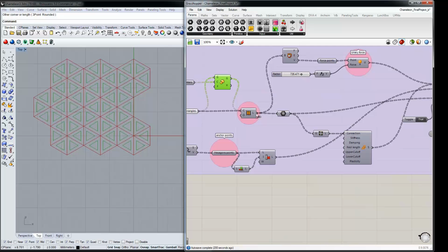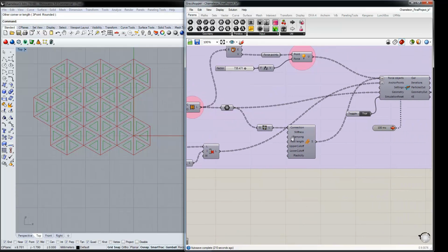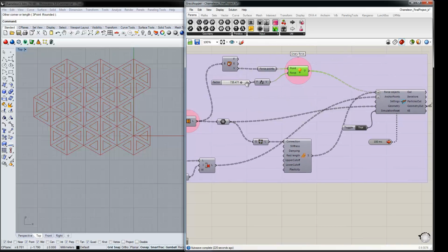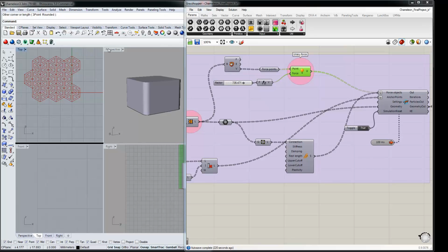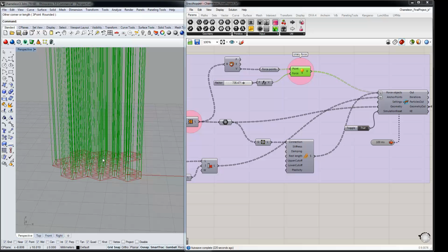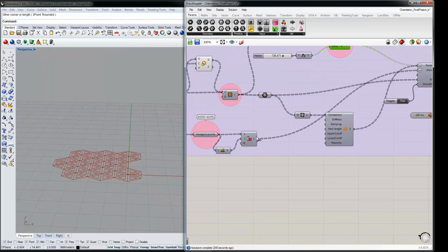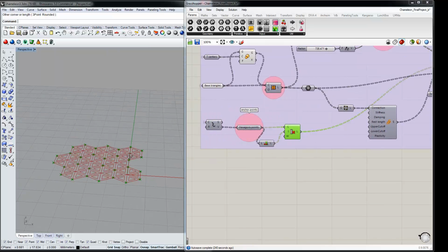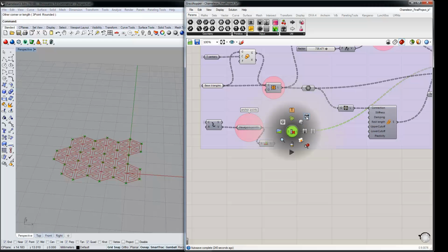And then I lofted them, then I used this mesh and Weaverbird to get the connections for the spring, and I use it for the first object, and I again use the unary force that I apply to all the nodes of the mesh of the hexagon, and the anchor points are all of the points on the edges of the hexagon. So this is the result of the Kangaroo.